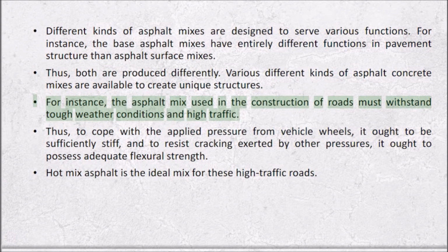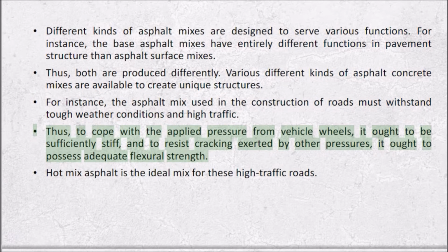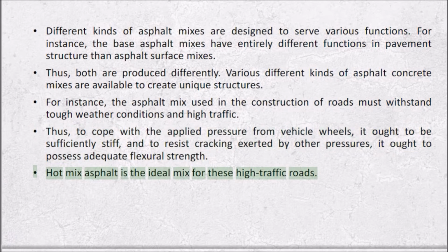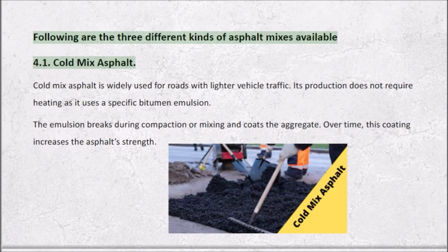For instance, the asphalt mix used in the construction of roads must withstand tough weather conditions and high traffic. Thus, to cope with the applied pressure from vehicle wheels, it ought to be sufficiently stiff, and to resist cracking exerted by other pressures, it ought to possess adequate flexural strength. Hot mix asphalt is the ideal mix for these high-traffic roads. Following are the three different kinds of asphalt mixes available.